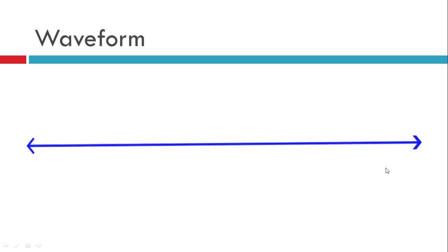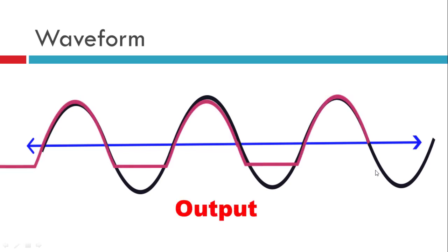If we go on applying the entire series of waves, this is the input and this is what we will get as the output. The red one is the output. So with this you can see the negative part, we are getting the clipped negative wave, okay, so it's called a negative clipper.